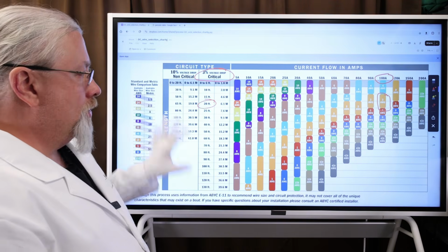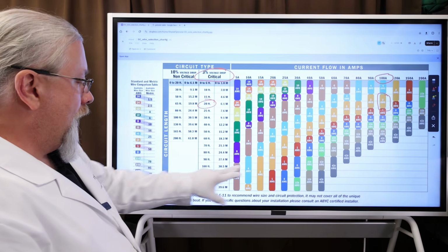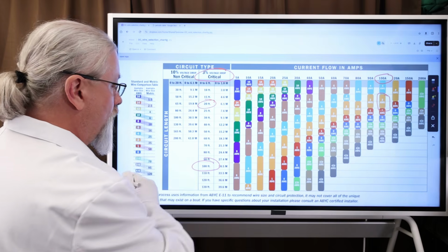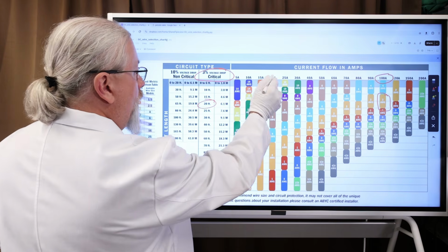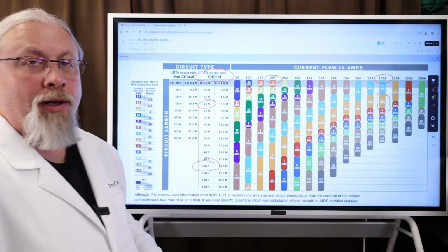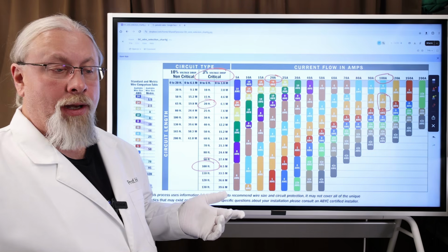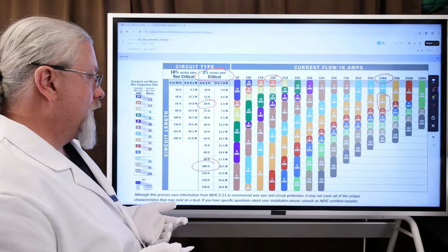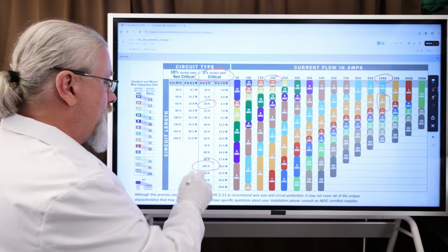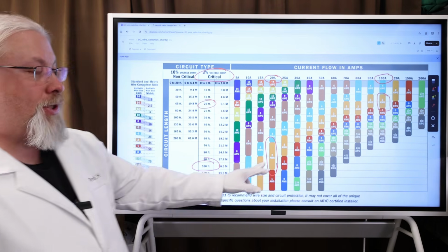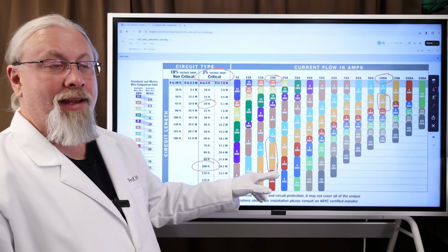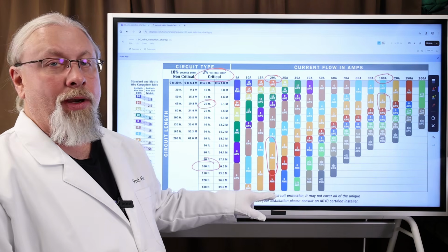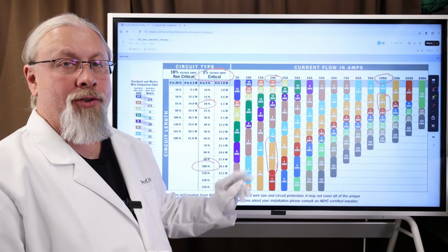You can use this at your own time and check it out and see. If you're running solar, you may be running a 100-foot cable for solar. And at 100 feet, you might want to do 20 amps, because 20 amps is typically what a solar cable would require if you're running it over a long distance. So at 100 feet, 20 amps, it says right here, you're supposed to use a 2 AWG. So you can see here that running very long distances requires you to pretty quickly use a lot larger cabling.